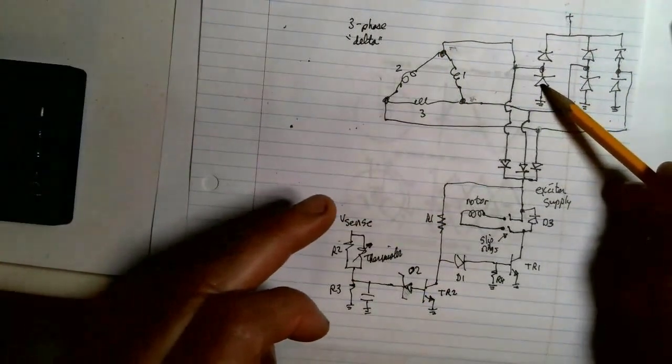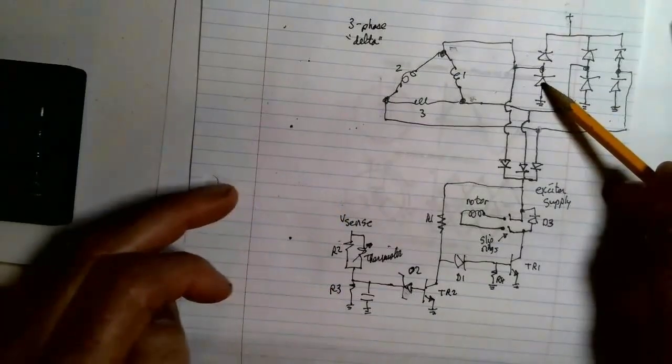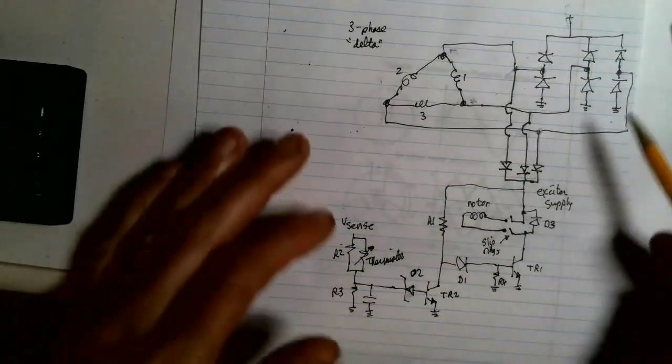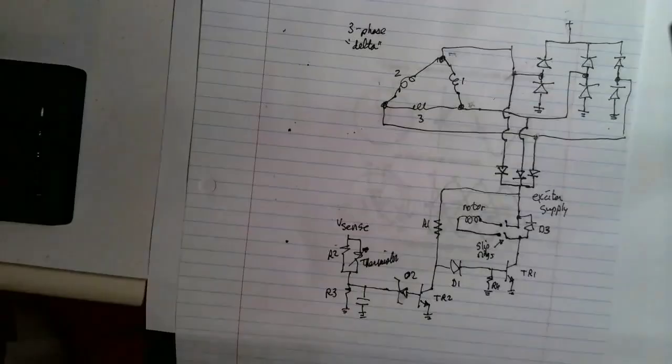Okay, so you can see that all 6 of these diodes turn on. They turn on 2 at a time, but different ones at different times, and so they kind of strobe. If the diode was lit up when they were on, they kind of strobe back and forth like this as the rotor turns. So that is how the rectifier works.